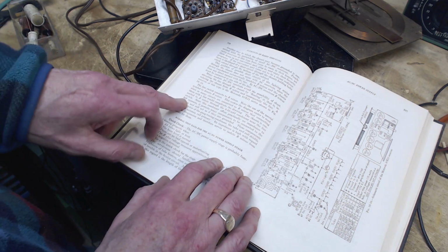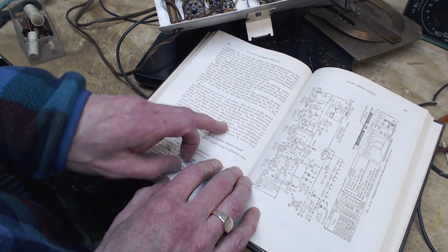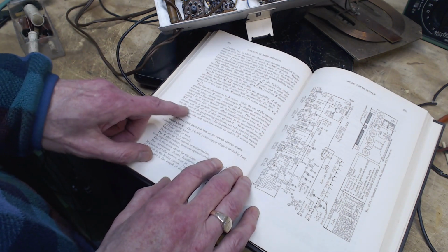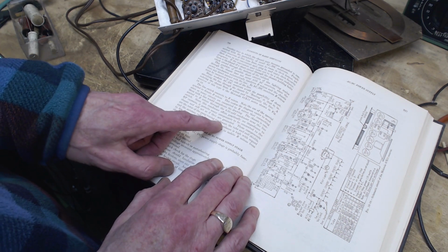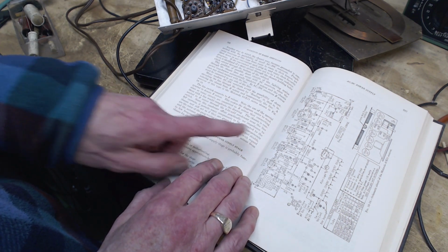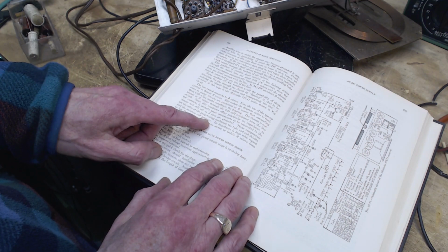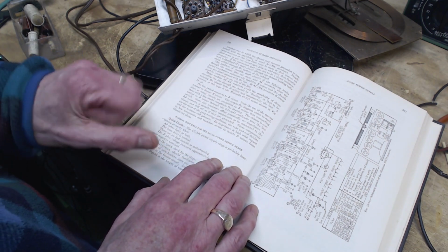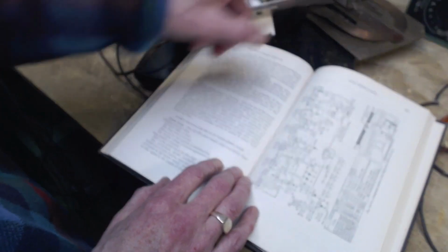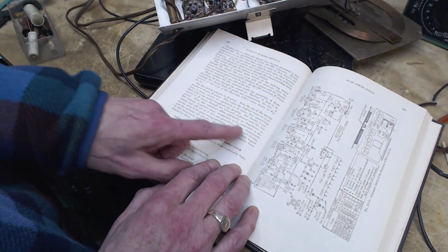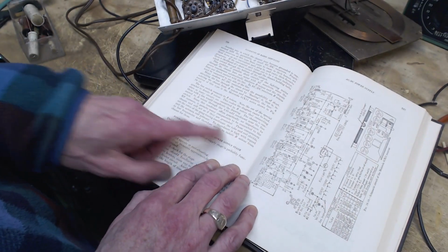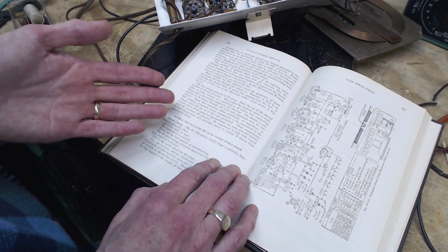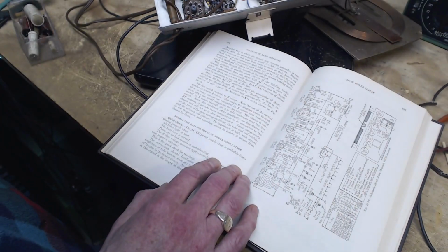Oh, I see what it's saying. I wish they wouldn't use the word grounded. These components are the rotor of the gang tuning condenser, the tube and coil shields, and the antenna coil primary. Yeah, often in a radio you'll see that these things are tied to the chassis, but nothing else is, except through the capacitor. The B minus is through the capacitor. Its impedance is high with regard to low frequencies and therefore serves to isolate B minus from the chassis for them. And the low frequency they're talking about is 60 cycles of power coming in.